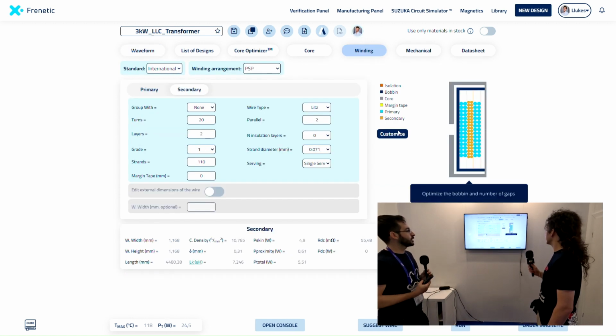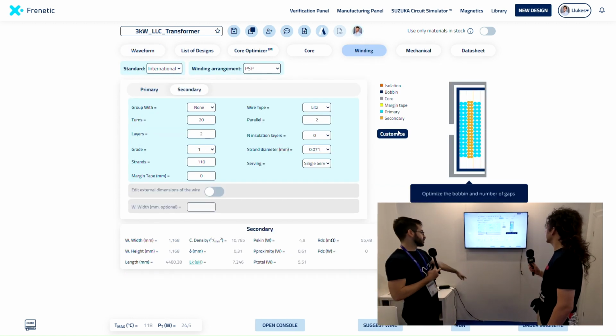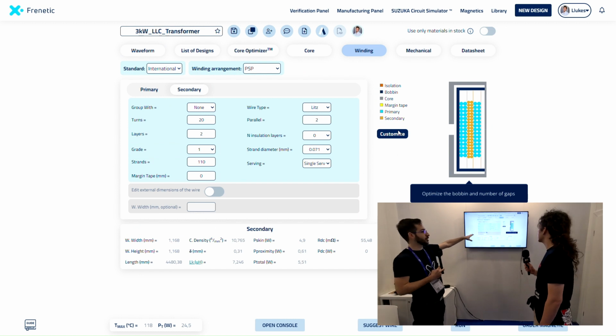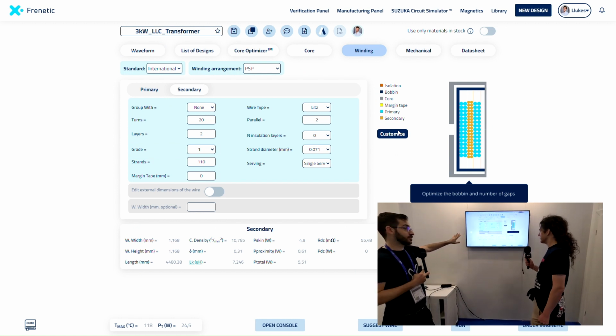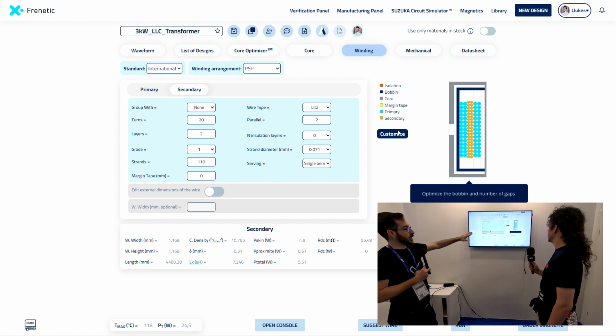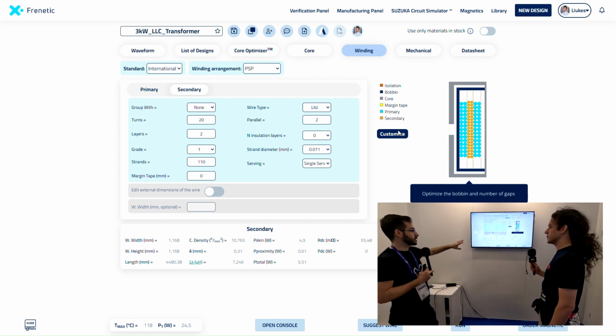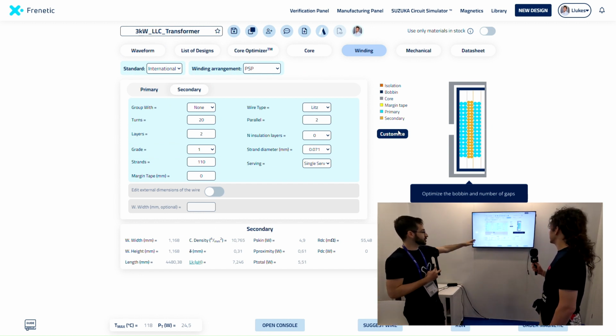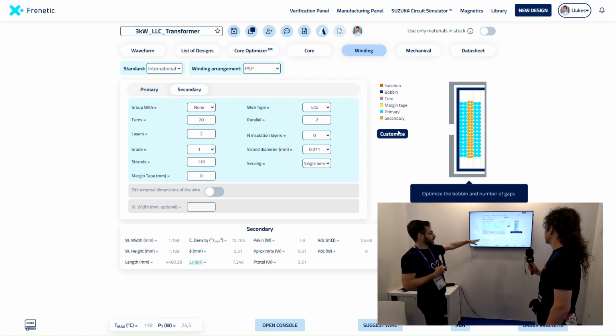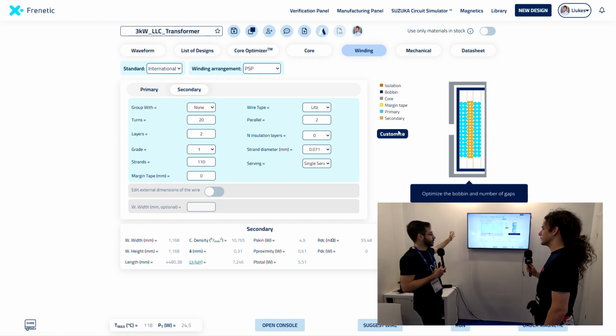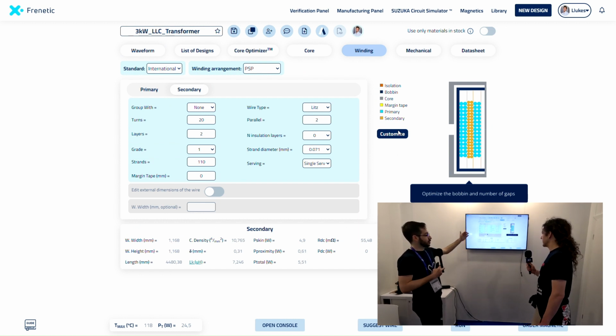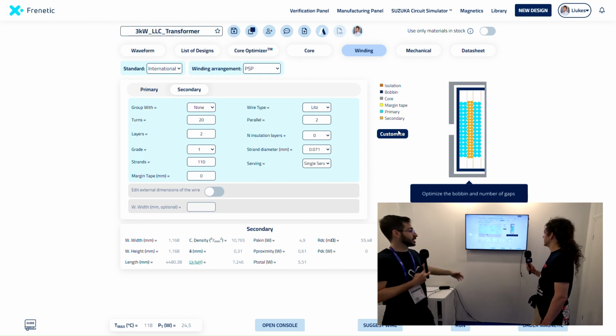And another thing which is very powerful is the prediction of the leakage inductance of the transformer right from this point before even building it. So you can move layers around and see that happening. Also, you see all of the losses calculated for the windings. I mean, core losses, we saw that, but skin, proximity, fringing field included in the proximity effect, DC losses, if any.